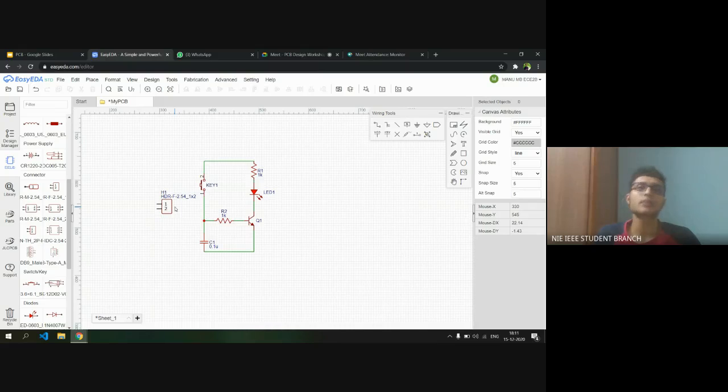You might ask where you'll be using screw terminals or headers. When mechanical stresses are concerned, we usually go with screw terminals, where you open the screw, insert the wire, and just tighten the screw. That time the wire is held fixed in the screw terminal, therefore it doesn't move. If a circuit is not bothered by mechanical stress, then we can go with the female headers.